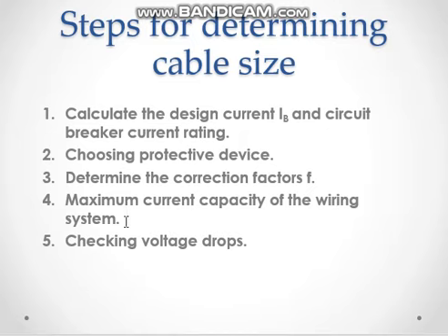But once you get this size of the conductor, please check the voltage drop that can be allowed by your conductor, and you have to make sure that this voltage drop is below the allowed value of the voltage drop.